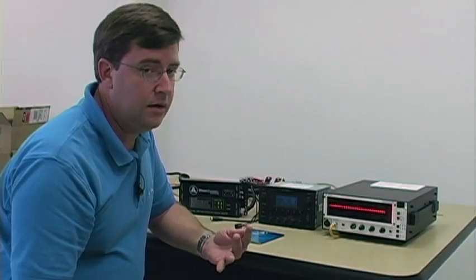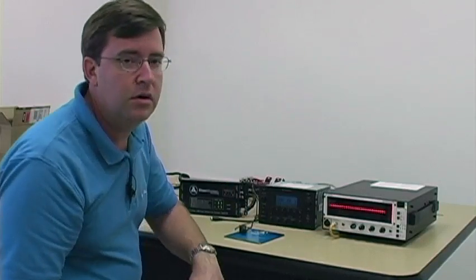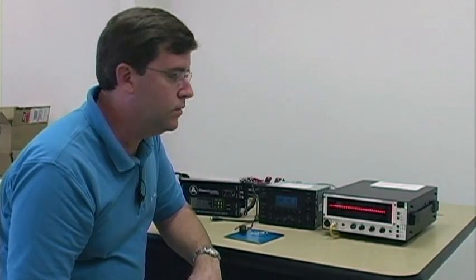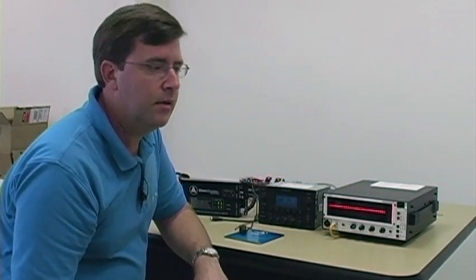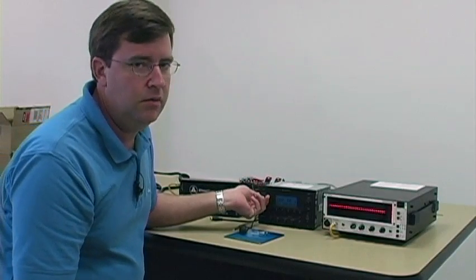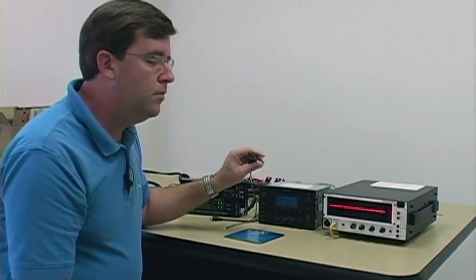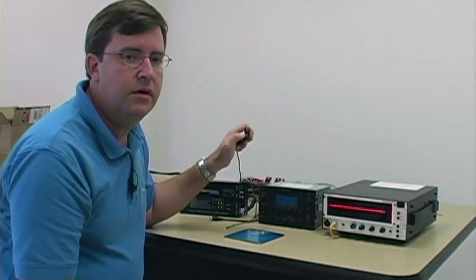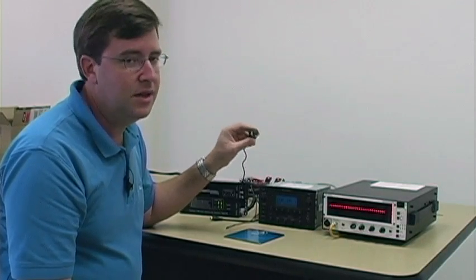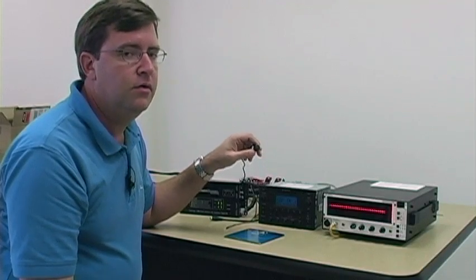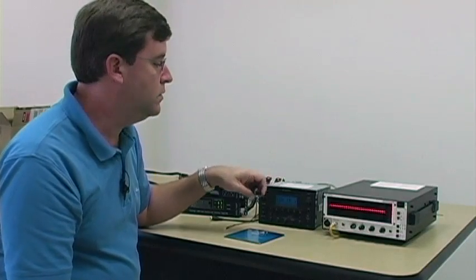The only thing you can't do, absolutely, if you don't install the knob is use the aux input on the CleanSweep for an additional source. You'd have to interface any aux sources through the factory head unit at that point because this becomes your only volume control in the system. So it shouldn't be a deal killer ever if the knob isn't desired in the installation for one reason or another, although it is the cleanest way to do it and gives you the absolute flattest frequency response. It's certainly not the only way to use a CleanSweep.